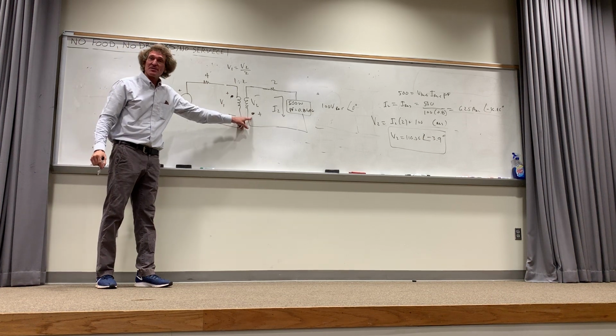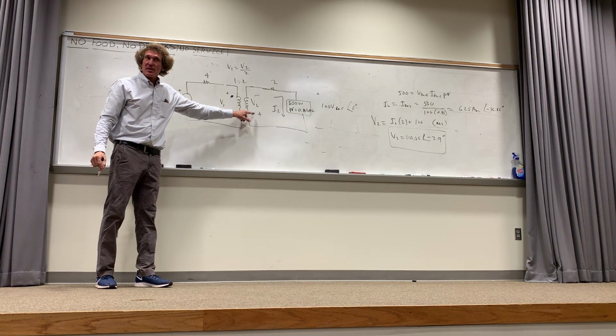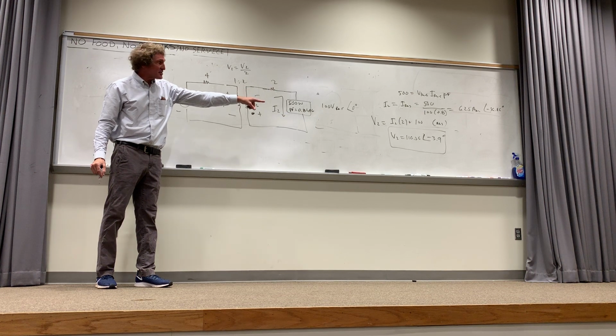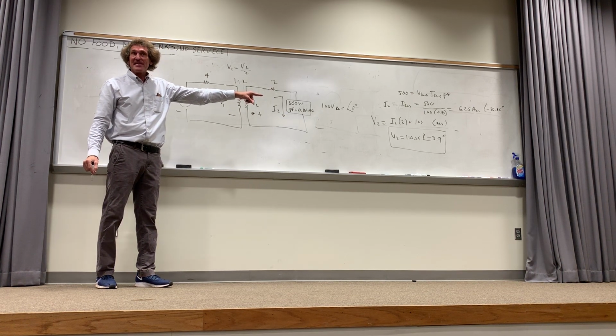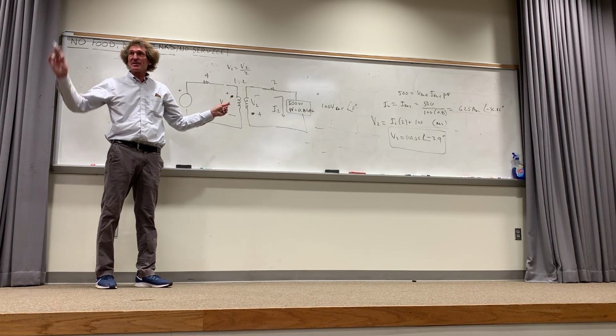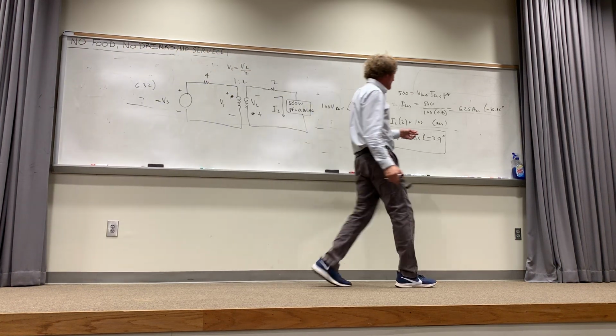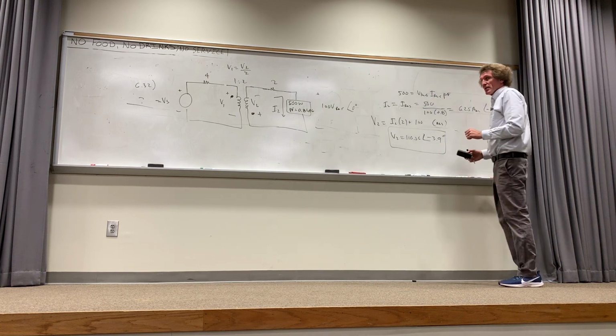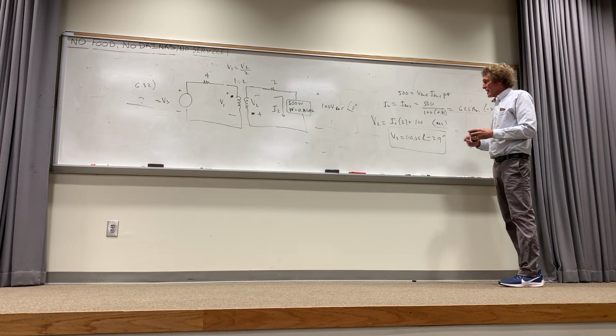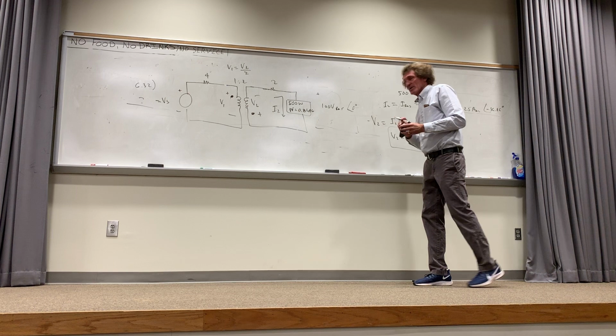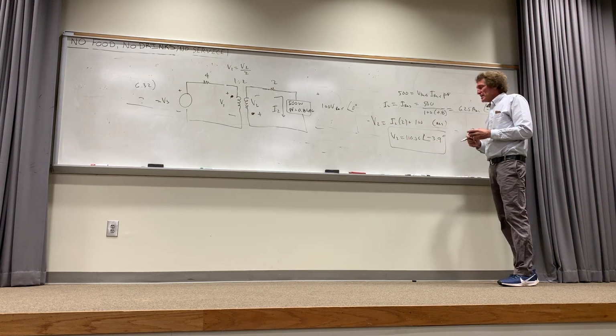Because the plus is always at the dot, isn't it, class? Plus to minus. The V2 that I actually put there is what? Negative that, isn't it, class? How many see this? So what I'm going to do to correct that is take this and add 180 to it. You follow me? Then it'll be right. This V2, this is actually minus V2. Add 180 to that, and what do you get?